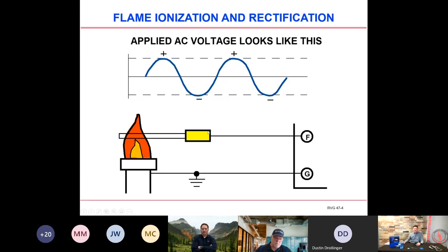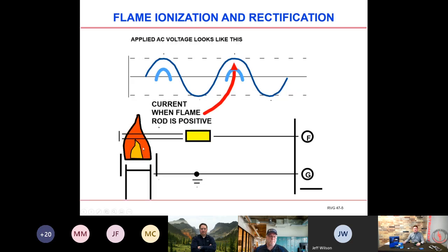So just be cognizant that when you do have this flame circuit powered up, there is a high voltage coming out on this F lead through the flame rod into the flame envelope. So the AC signal is applied. It makes contact with the ionization that's happening around this flame, and then continues down through the actual burner assembly down into the ground.